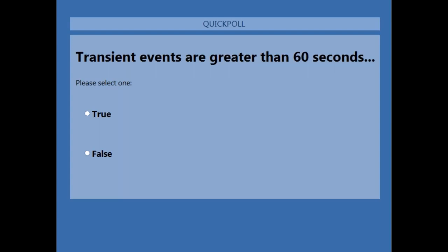Next question, Steve. Have you ever had to perform vibration monitoring caused by human traffic within a building to conform to design requirements, namely elevated floor systems? Yeah, we've been asked to do that a couple of times. Those vibrations are a lot more sensitive, again, because humans are more sensitive to vibrations than structures.